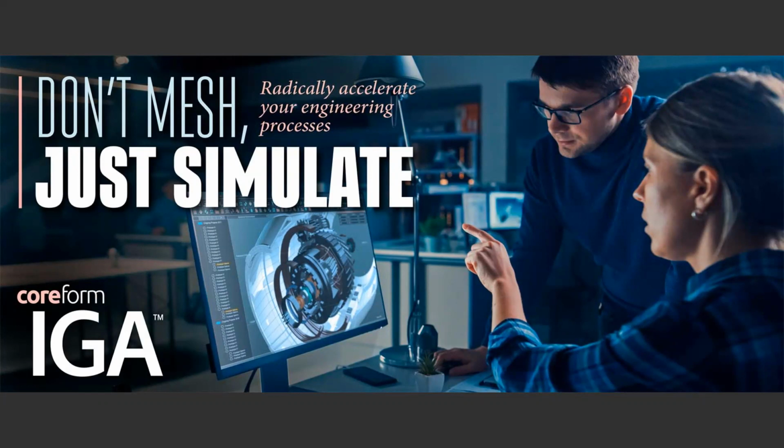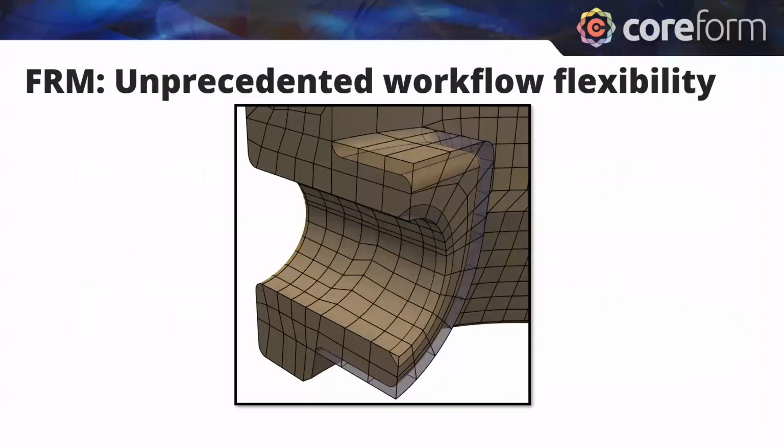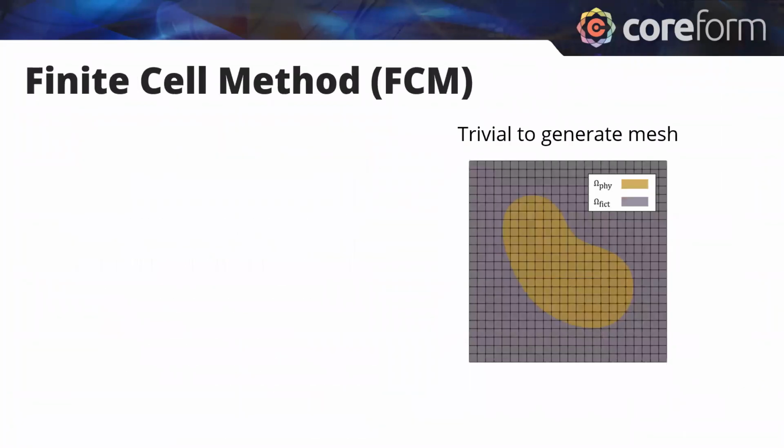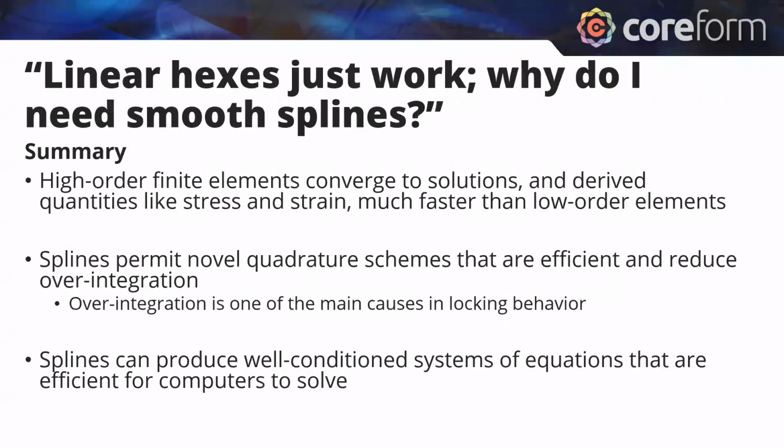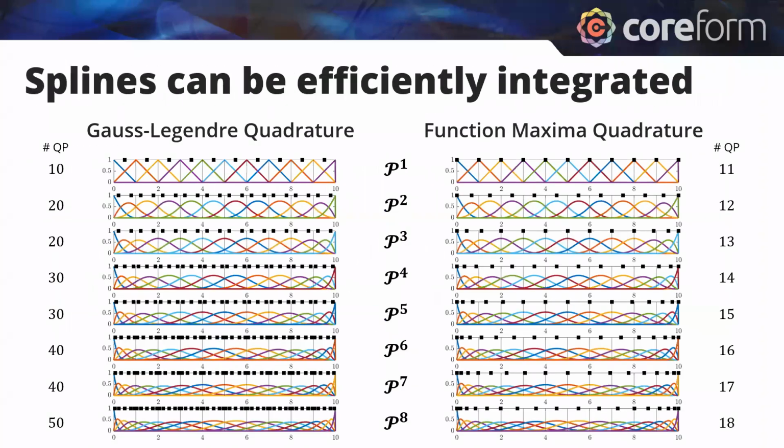From Arthur, wouldn't higher order elements lead to much denser stiffness matrices? So they do result in denser stiffness matrices, but the difference is that those stiffness matrices are then much smaller. I've got some specific examples in some backup slides, but I can talk to it here. If we look at the quadrature slide again, I have only 18 basis functions in this 10 element